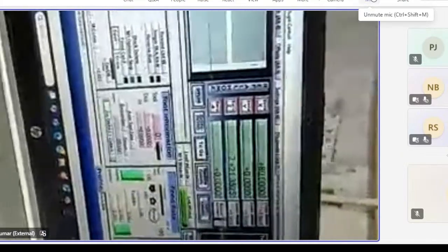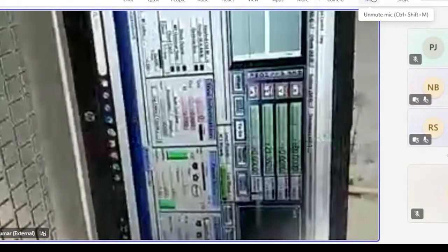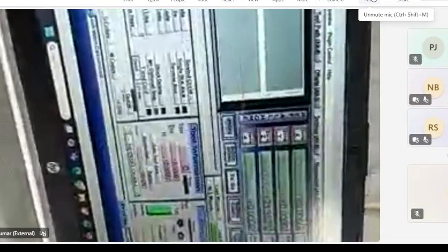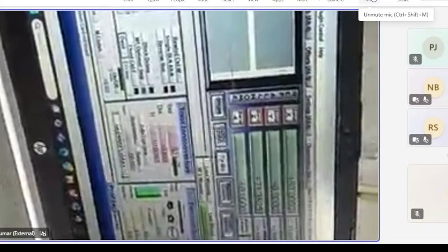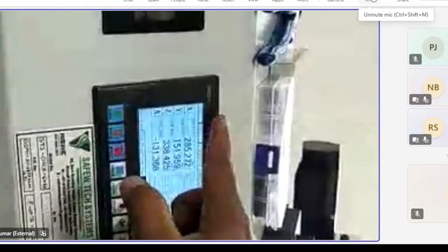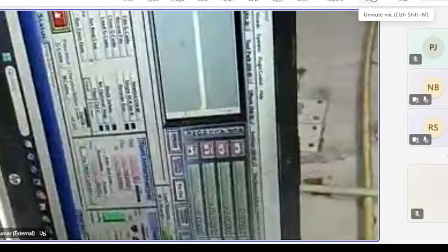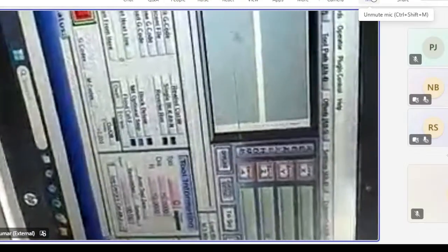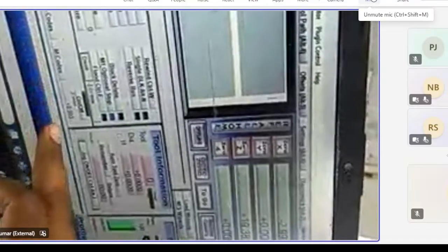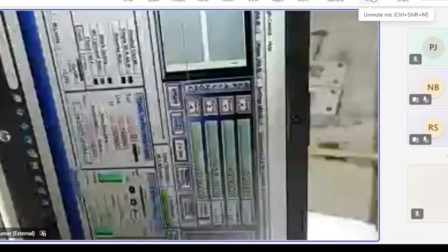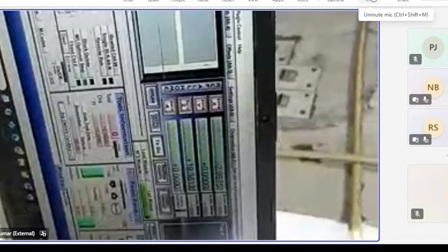So what we will do is use this cable to connect the controller to the software. After this, we have to change the mode over here. Then we have to go into the continuous mode. And once we go to the continuous mode, then again go to the reset. Then it is showing e-stop configuration. Now you can see there is no problem showing. If it shows the emergency stop, it means the configuration card is not connected. Then we attach the controller part to the software.